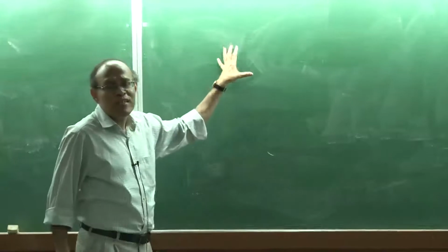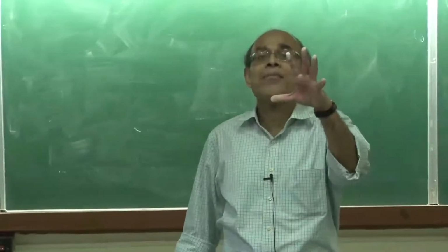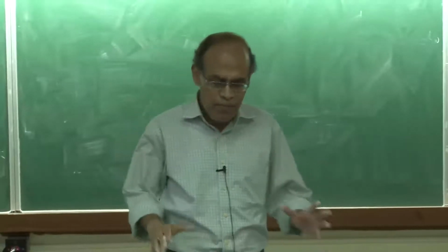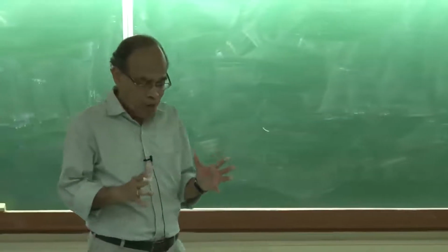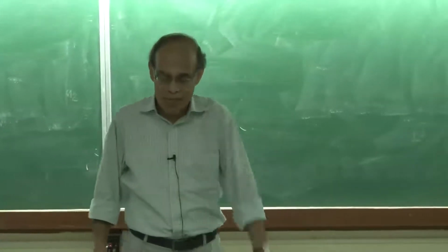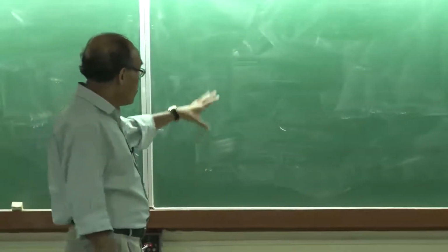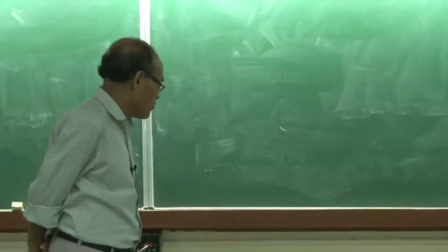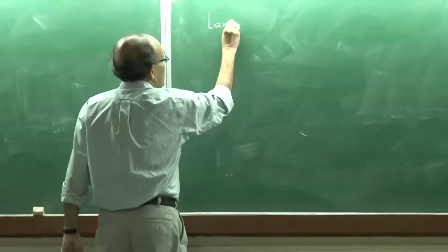In the Bernoulli's equation, if you remember, I think it was done just a couple of minutes back, I introduced the parameter beta in the kinetic energy term, and I said that beta assumes a value of 0.5 for laminar flow and beta is equal to 1 for turbulent flow. The way I initially wrote the Bernoulli's equation, I said it is valid for turbulent flow. On the other hand, by introducing the parameter beta equal to 0.5 in the expression of the kinetic energy, I said the equation can be made applicable to laminar flow. Now, these two terminologies need to be discussed extensively.